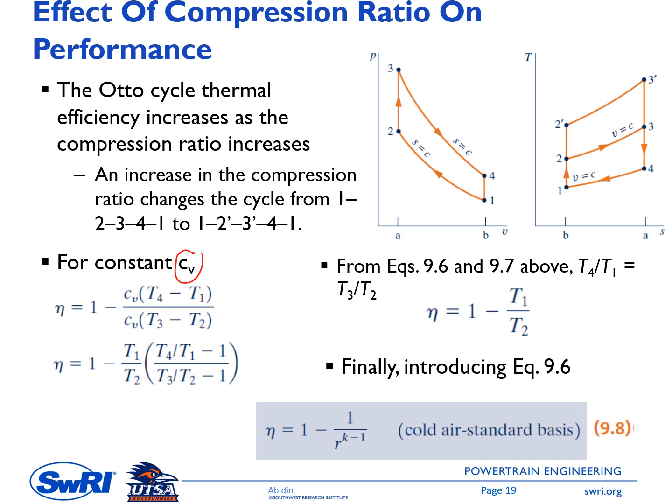From the thermal efficiency, we know that the formula, I believe, is 1 minus (U4 minus U1) over (U3 minus U2). Because we assume that Cv is constant, you can replace U4 by CvT4, you can replace U1 by CvT1, and so on, so you will get this formula.